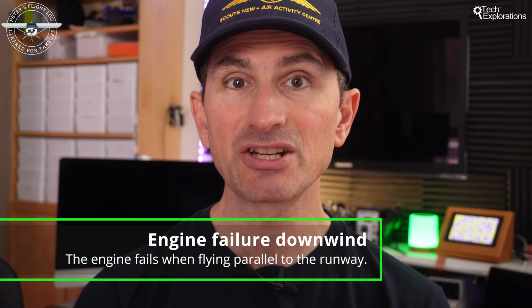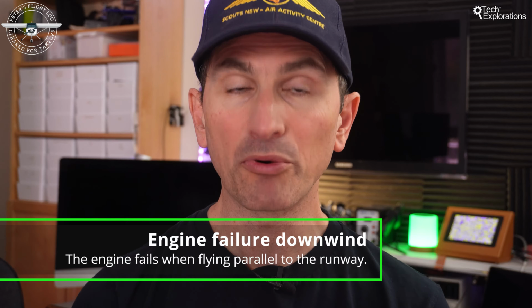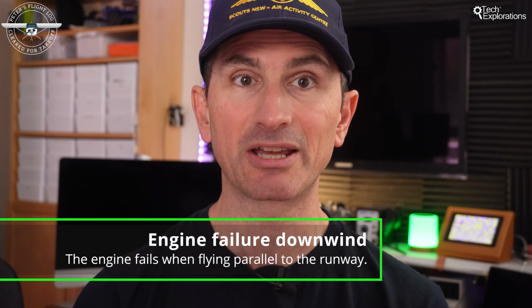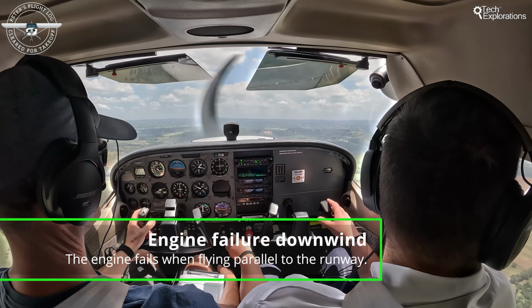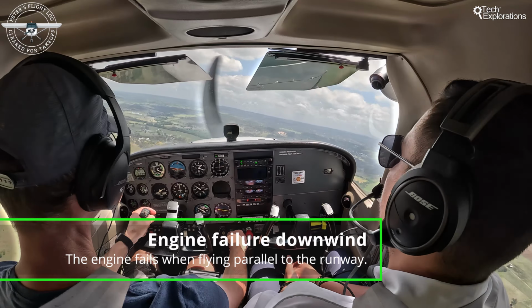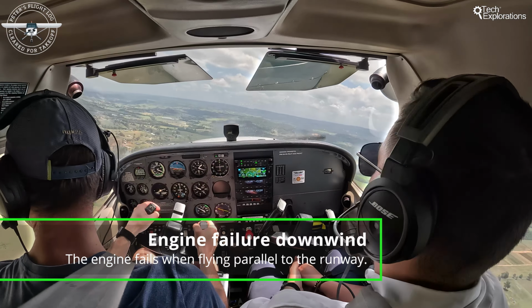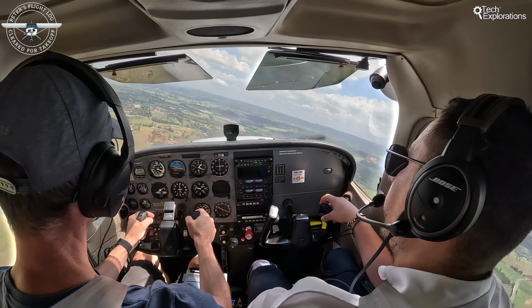Continue. An engine failure at downwind occurs when the engine fails while you are flying parallel to the runway but in the opposite direction of landing or taking off. This is part of the traffic pattern you typically fly around an airport. The engine could fail for various reasons, such as fuel starvation, mechanical failure, or even pilot errors like incorrect fuel mixture settings.